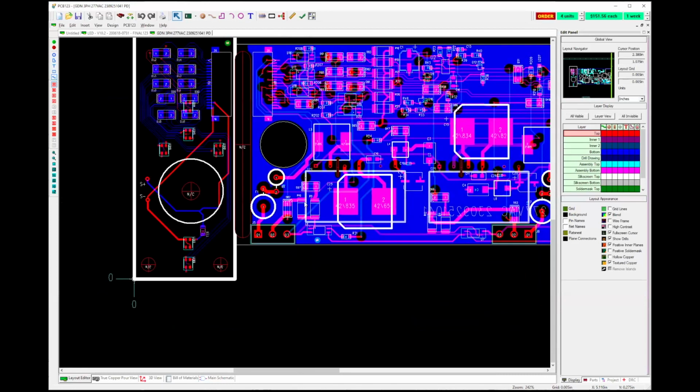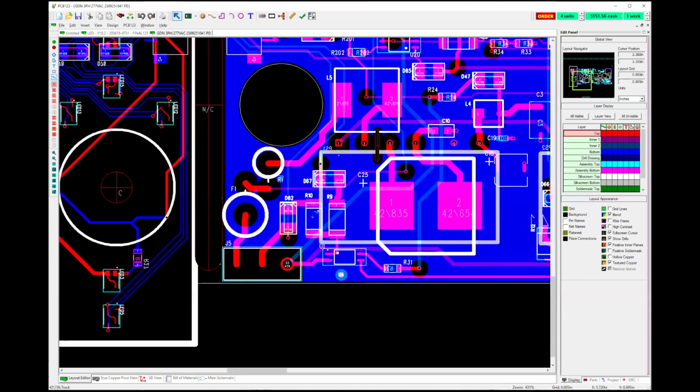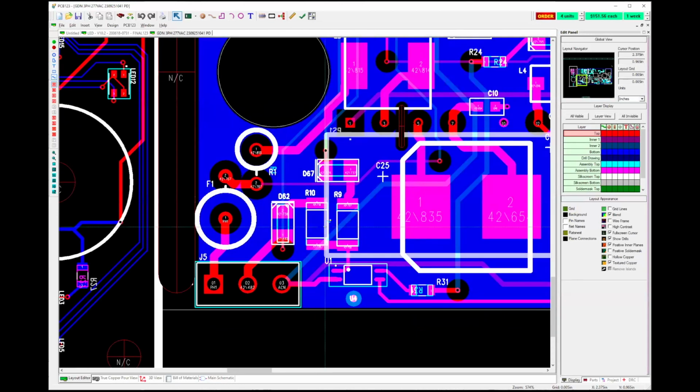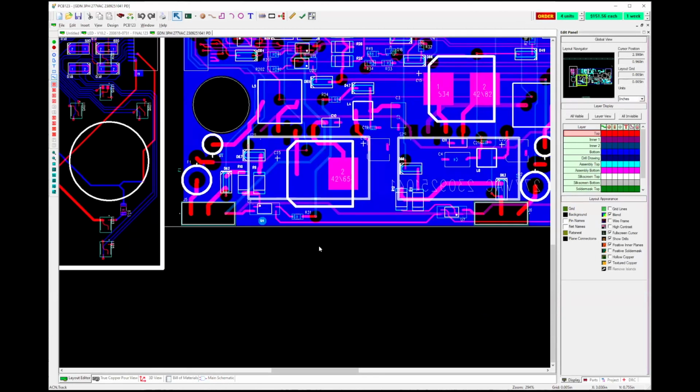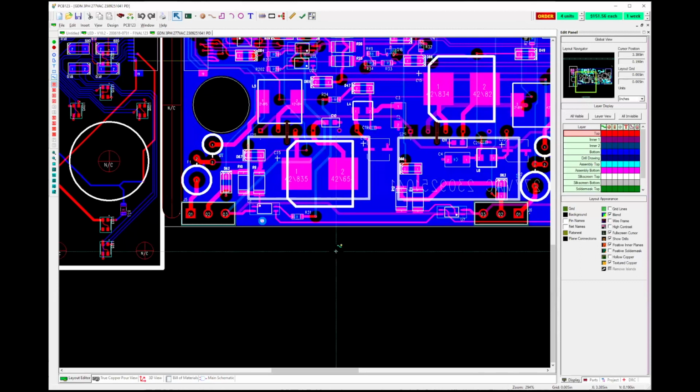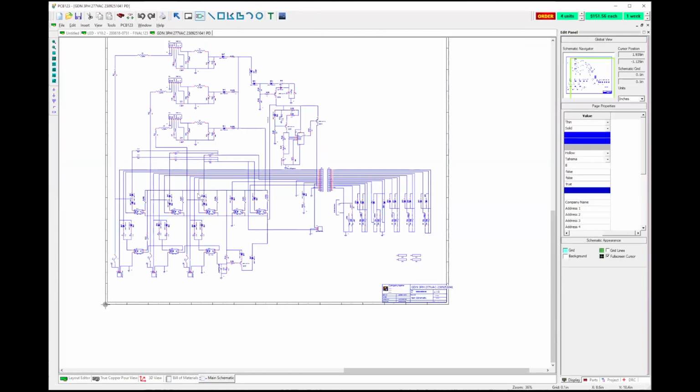You can zoom in on it, take a look at what's going on, and then place it where it goes. You'll have guide wires on all of your parts to tie them all together, but when they're spread out randomly from before you place your parts, it'll be pretty hard to follow. And it's kind of a dynamic thing. If you move a part to another location, if it's connected to more than one place, that connection might change to that other part. So you can't really just say, oh, the guide wires go from here to here, so I'll just hook them up by that. It's better to use your schematic to drive the placement of the board.